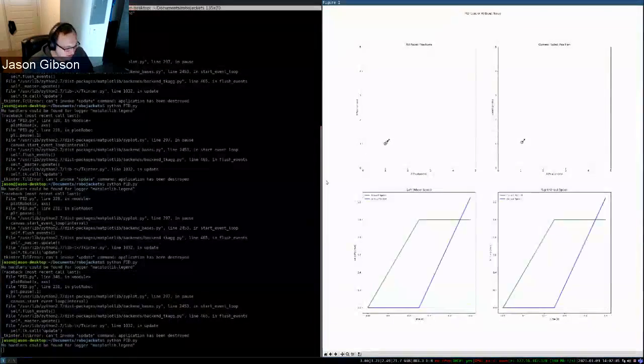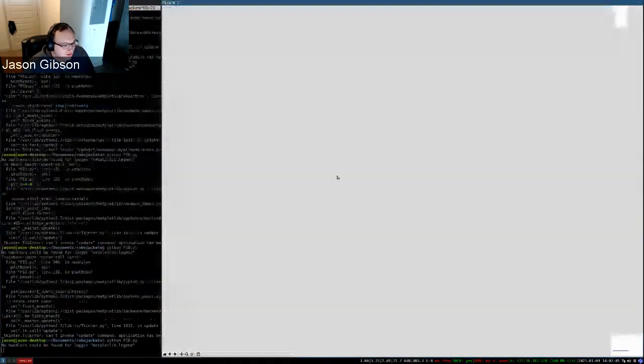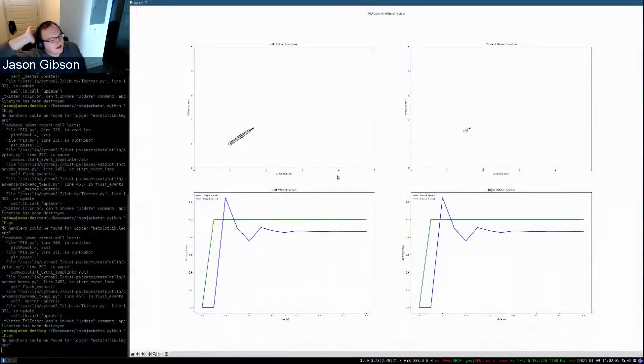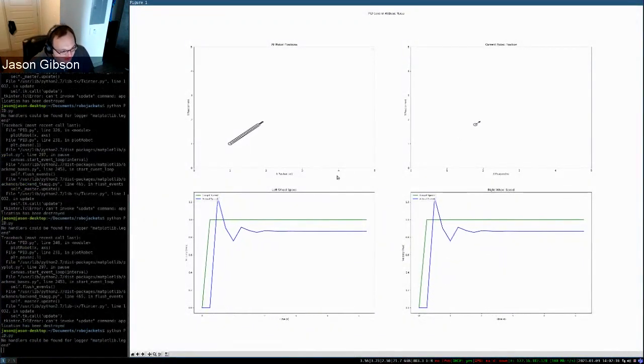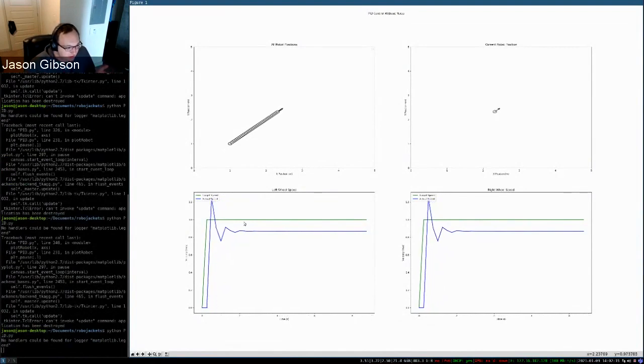So I'm going to replay the simulation. Now, the behavior we're seeing, the more technical term for it, is steady state error. Essentially, that means we're converging to a value that is not our set point. What we're trying to do is the green. We're trying to get the blue to go to the green. I left that out earlier. I apologize.